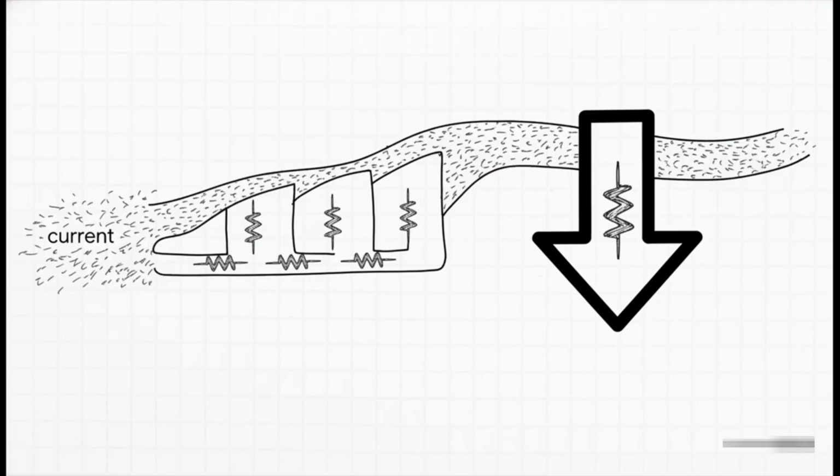So what if you wanted the exact opposite, the minimum resistance? You'd connect them in parallel. By opening up all those extra lanes for the current to flow through, you make its journey way, way easier, and the total resistance just plummets, all the way down to a tiny 1/25th of an ohm.